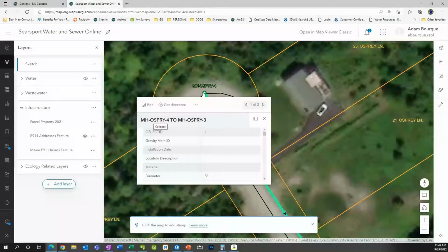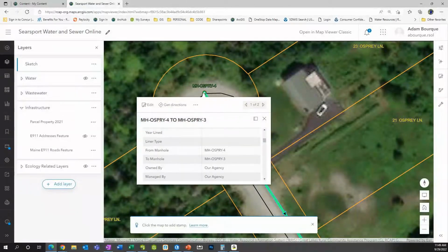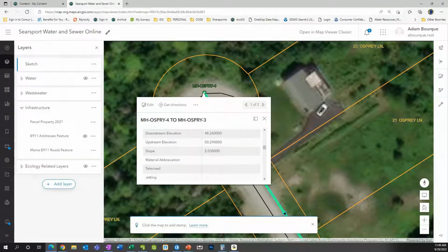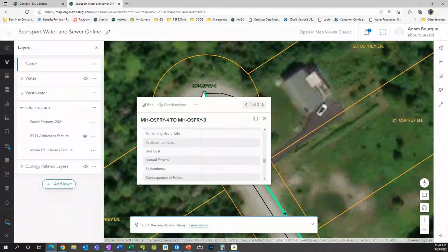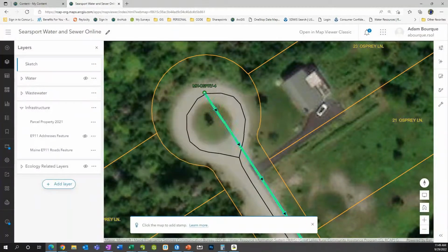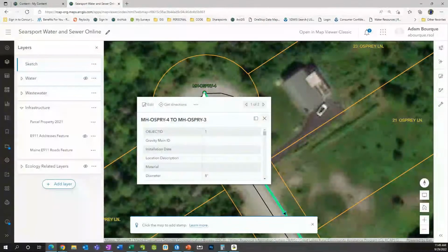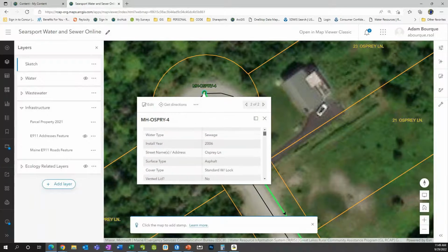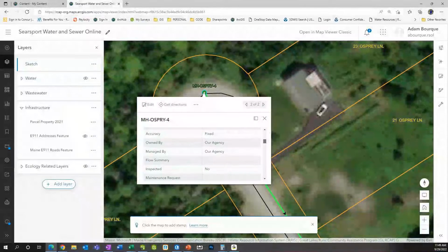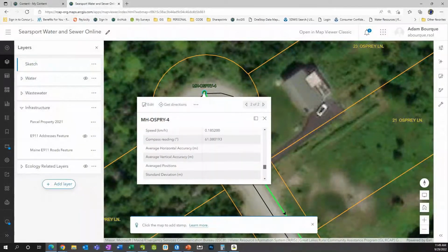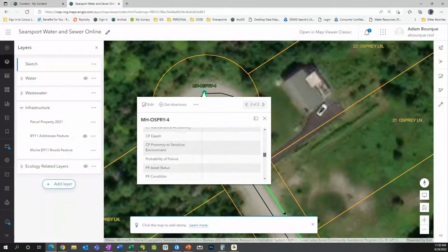Doing the asset IDing again, this is the sewer line. We're going from this manhole to the next, and having that as the title there, having the diameter, and then from there we can get our surface elevation from some online sources with the manholes. Like Maine, they had 5 feet. I'd have to look into what elevation data is available for New York, but probably the same. Sometimes it's 2 feet or even 6 inches that we could get the surface elevation down to. That's the accuracy.